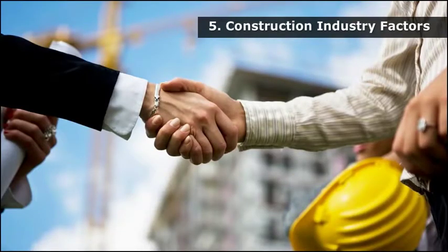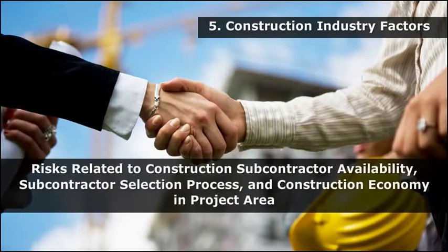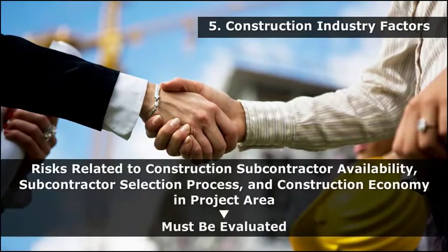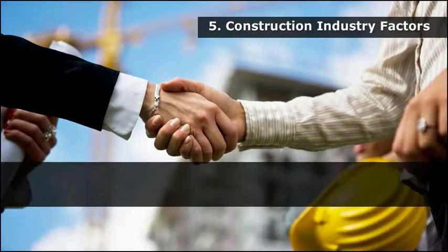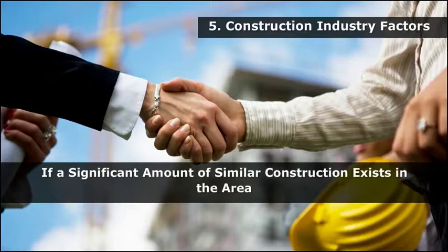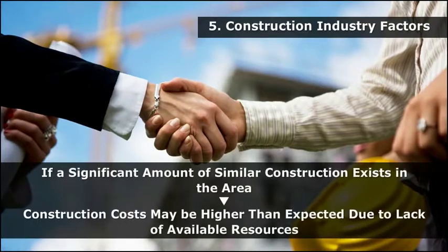5. Construction industry factors. Risks related to construction subcontractor availability, subcontractor selection process, and the construction economy in the project area must be evaluated. If there is a significant amount of similar construction in the area, construction costs may be higher than expected due to a lack of available resources.